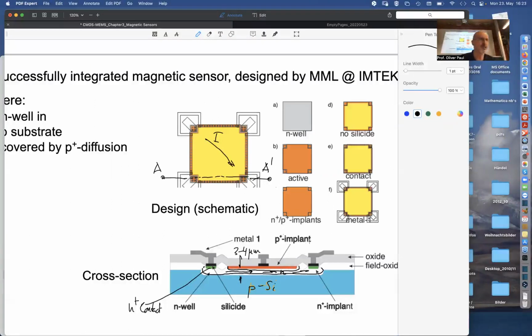Nevertheless, many sensors don't have that P+ in there, because you maybe don't care about the noise, since you're not at the limit of the signal to noise ratio. And then this P+ needs to be contacted also, of course, to be put at the right voltage, because you would like your PN junctions to be reverse biased all over the place.